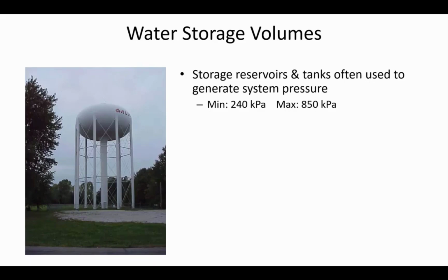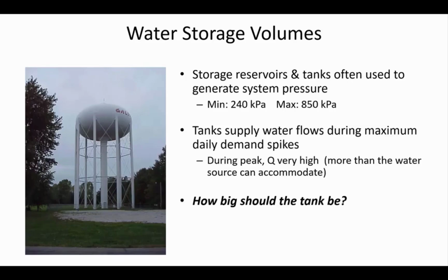Just to ensure resilience of our system, we have to size it so that all of those demands could occur simultaneously, and we're still able to provide the needed volume of water at the minimum acceptable pressure. But that's not very often. Most of the time the demands will be much lower, and so we're going to be closer to this maximum pressure. And the maximum pressure is going to be observed during periods of low flow or no flow, like the static condition at night. So we want to pick a reservoir location that satisfies both of those constraints.